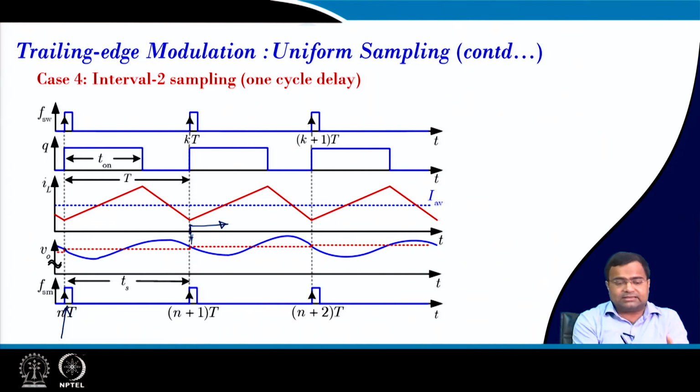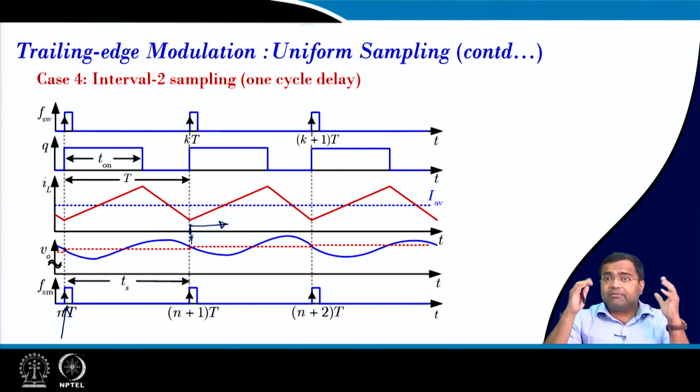But the bottom line is this one cycle delay is used to sufficiently accommodate the conversion time and the computational time, but this will also penalize in terms of loop delay. This will penalize heavily in terms of nonlinear phenomena, and we need to tackle how to make sure you can make your design stable even with this delay.